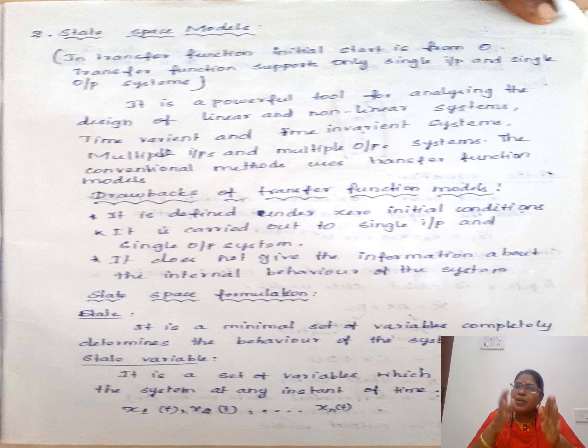So there we have various different controls we need to apply. After getting all these things, we need to control each one, and each control I'm considering as one state variable. X1 is the state variable for flow A, flow B is another, and the level of the tank and the temperature are the others. Like that we have four.